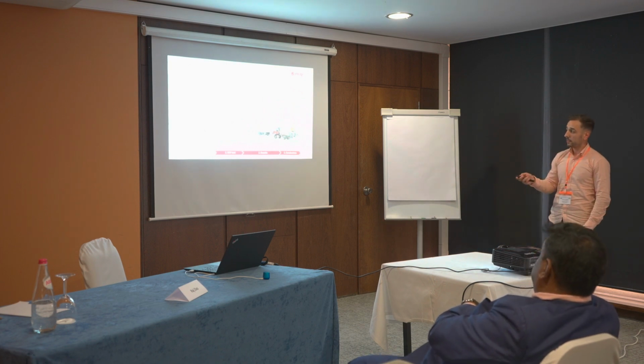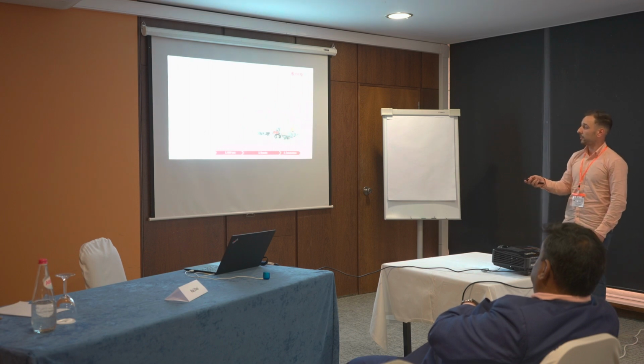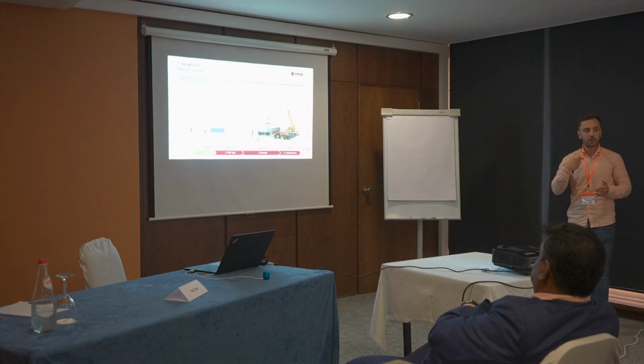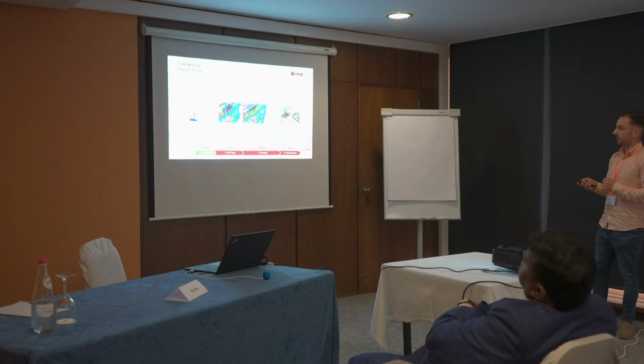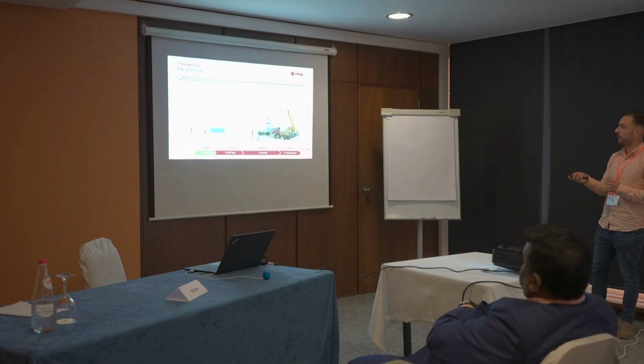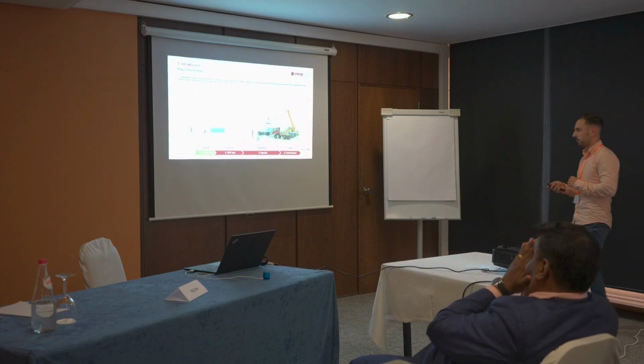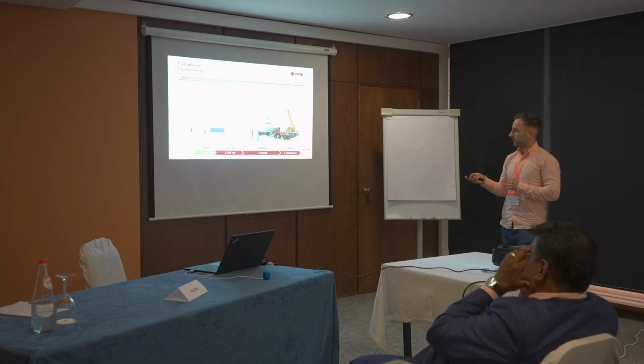and the striker with normalized dimensions will strike the front of the vehicle at a specific energy. It depends on the category of the vehicle. The pendulum should, in our case, transfer to the vehicle more or less 55 kilojoules of energy. Okay.